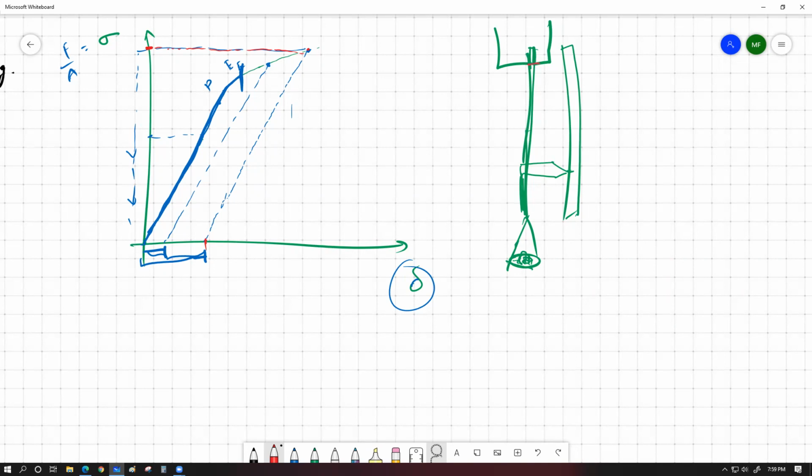For example, let's say initially the object was this much long. Let's say after we reach up over here, the object without the effect of any force is now this much longer. So this much is what we define as permanent deformation. How much work was done to achieve this permanent deformation can be found out by the area within this slice. This slice area basically gives us the amount of energy that is stored within this specimen.